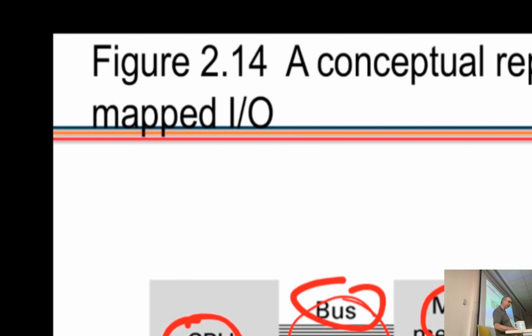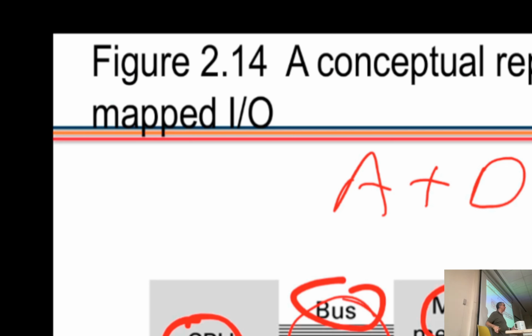So bus is actually address bus plus data bus. And there is also control bus, such as indicating whether I am reading it or writing it. Few more lines are control buses, read, write, or strobe, etc. There are some wires along with it, indicating what I am doing.